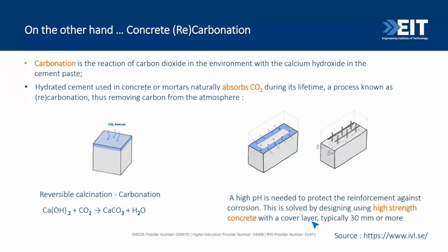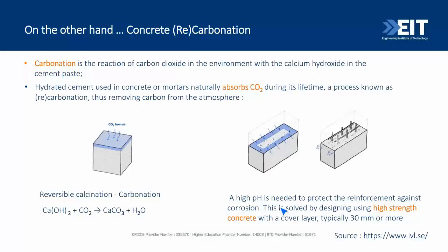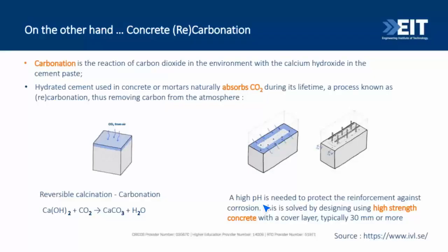Because, yeah, this is, Don, thank you so much. This is my main concern as well, because, you know, in terms of carbonation, when you have reinforced concrete, right? We need to be very careful in terms of the corrosion of concrete. And that's why we need to consider the cover, the minimum cover here is just a suggestion. So we need to pay attention to the pH of concrete. Otherwise, as you mentioned here, yeah, there are some pros and cons, as you can see.